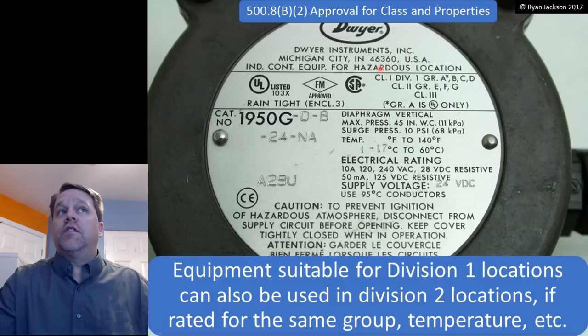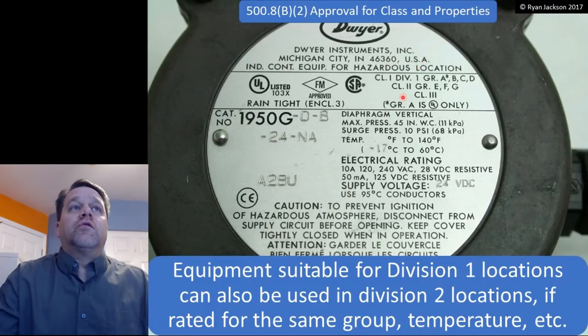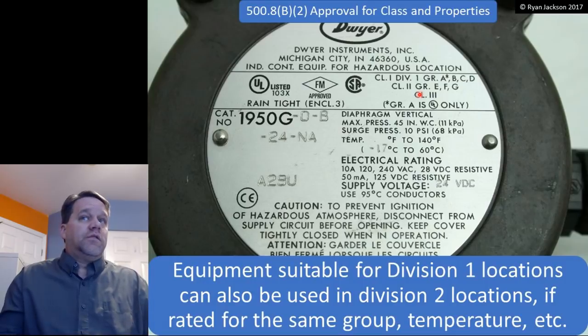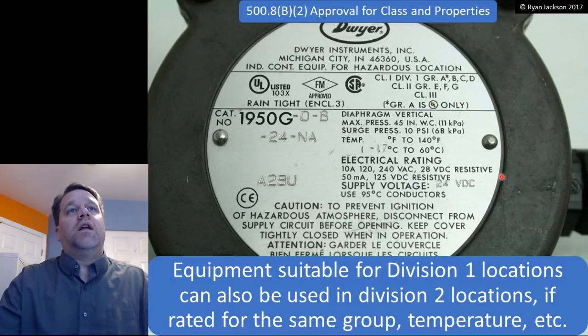So Class 1 Division 1, Group A, B, C, and D. Can I also use it in Class 1 Division 2? Yeah, of course. This says Class 2, Group E, F, and G. Well, is that Division 1 or Division 2? If it just says the class, then it's both. I can use it in Class 2, Divisions 1 and 2. Class 3, Division 1 and Division 2.